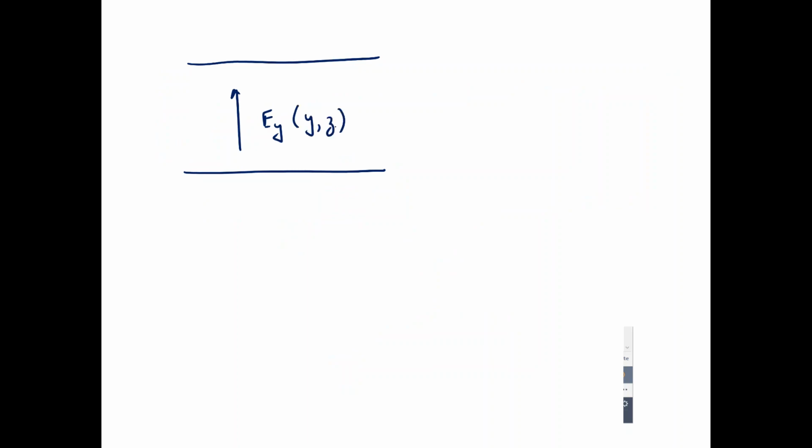And this is going to be another case of the solution. And the third solution is, if I have the same case now, electric field pointing in the y direction, but now the amplitude could possibly vary in y. I have two conductors, and in principle, the amplitude could vary in y. And if the amplitude varies in its own direction, then the z component of that field has to exist.